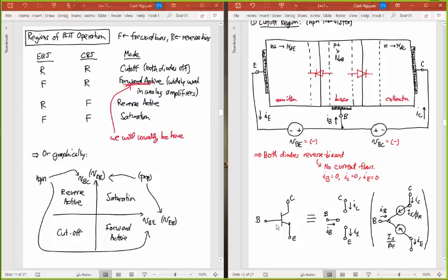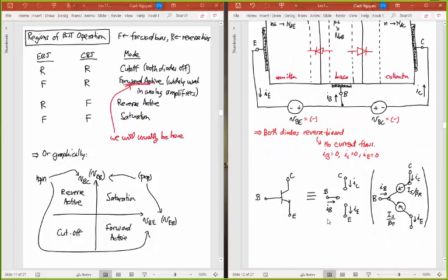And if I wanted to take this transistor symbol, where the collector is here, the base is there, the emitter is there, the emitter is the part with the N plus region, then this is the equivalent circuit. Pretty simple. It's just a big open circuit. And so if you ever have a circuit that uses this transistor, maybe you've got resistors and supplies around this, I would put those resistors and supplies around here, and then I would have an open circuit there. So this is the ideal model.